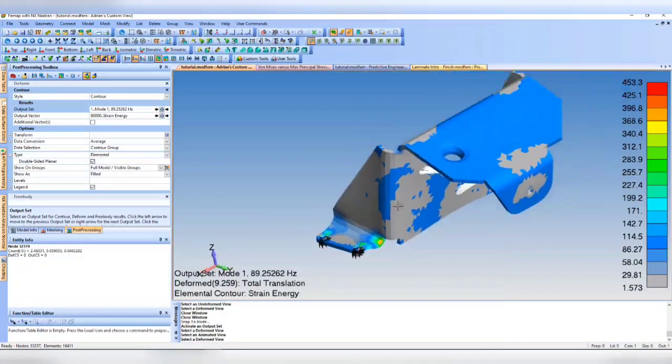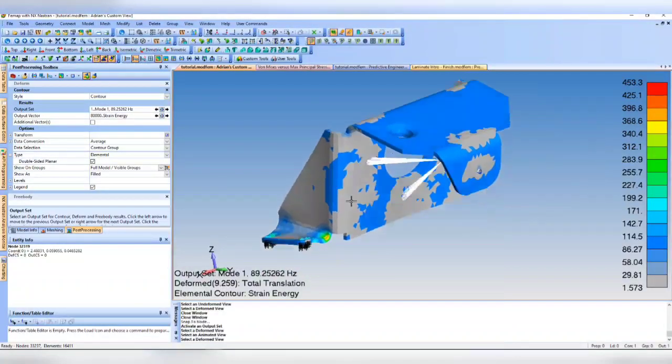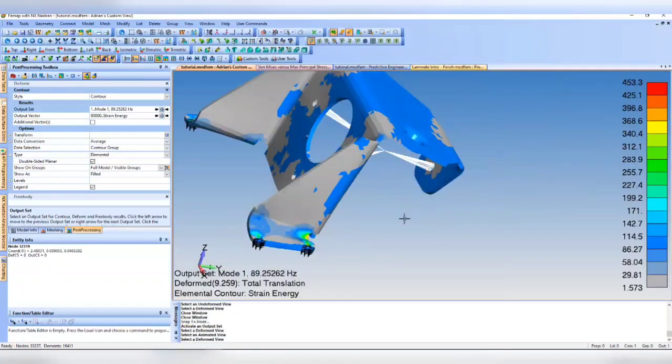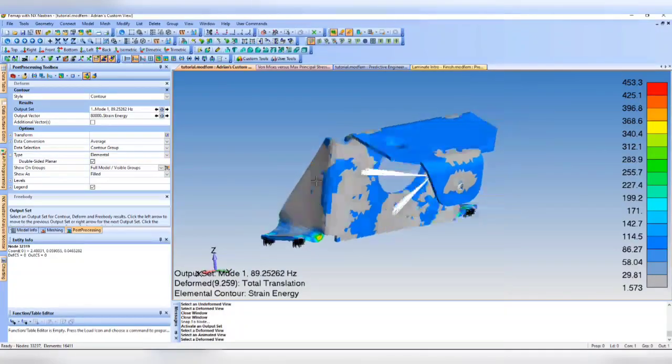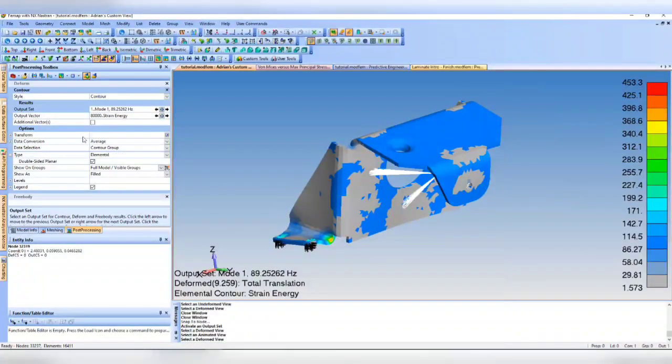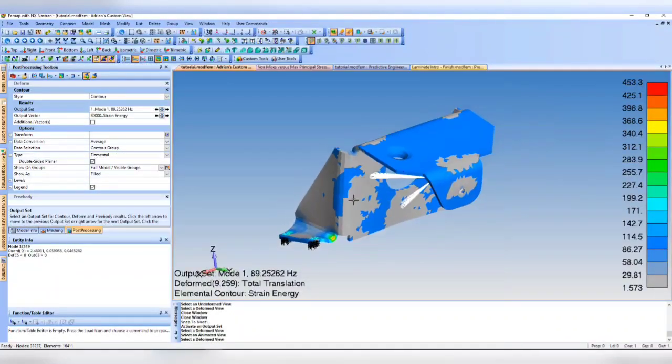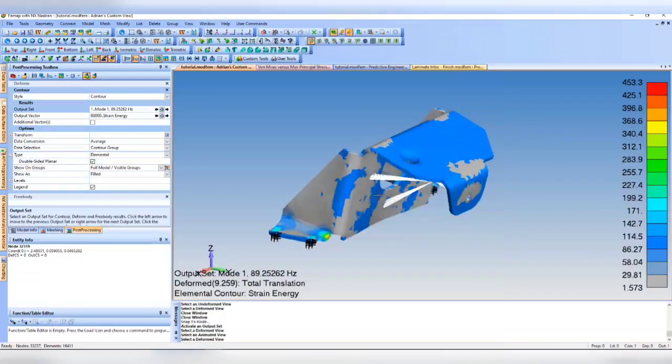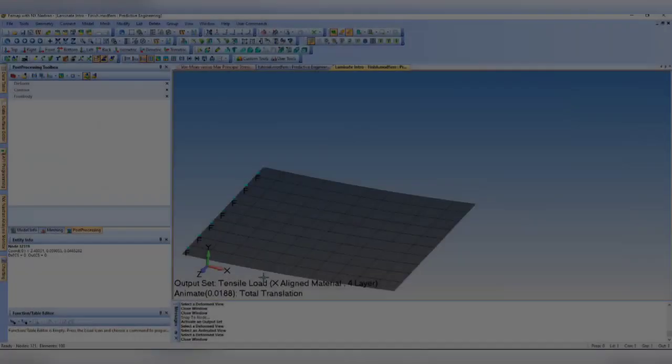You can change the materials as well. You can modify the geometry. You can put in a support like a strut. So a lot of ways to go about this, but you have the right idea. We want to avoid resonances that could occur when the forcing frequencies line up with the natural frequencies. Yep. Thanks for that assistance, Vinay. Those are all good ideas also.